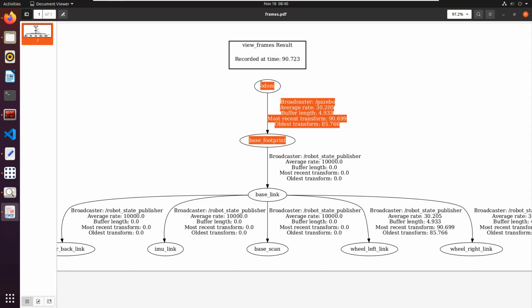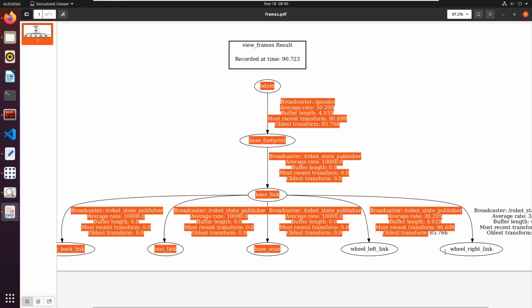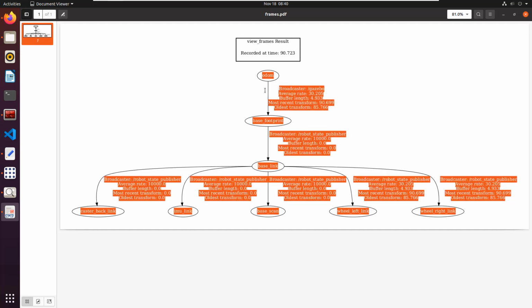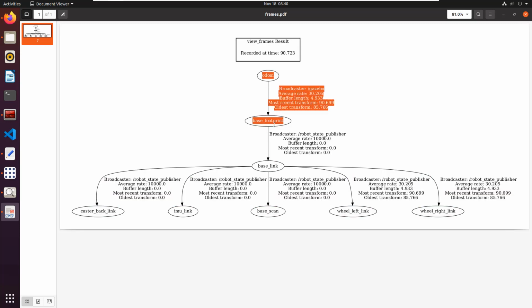The driver reads from the wheel encoders, computes the ODOM, and publishes the TF. So if you are having any issues with the ODOM to base footprint TF, this can also happen. You have to make sure you are getting this TF frame first, and after that check if there is any issue with the ODOM to base footprint, because that should also be correct.